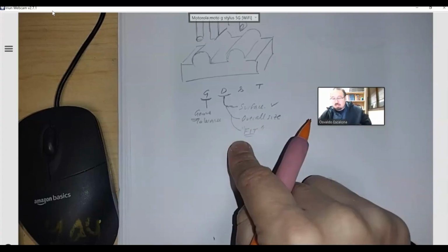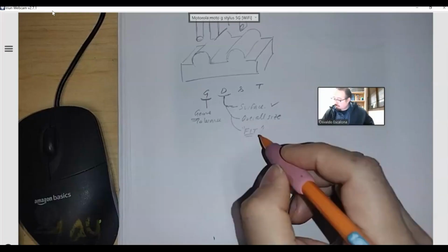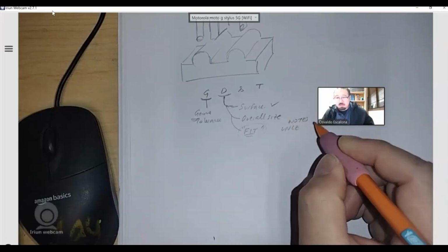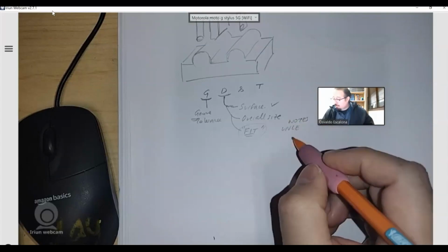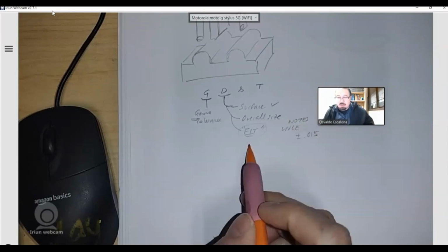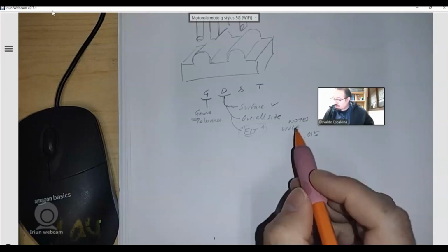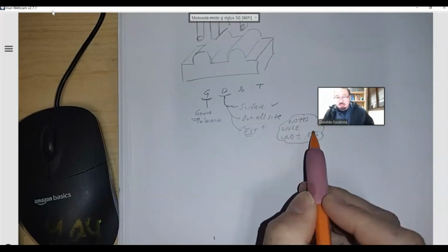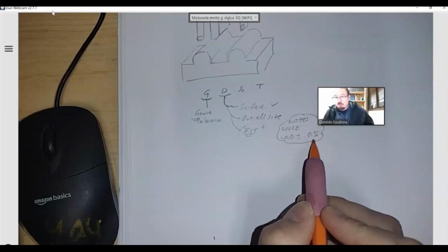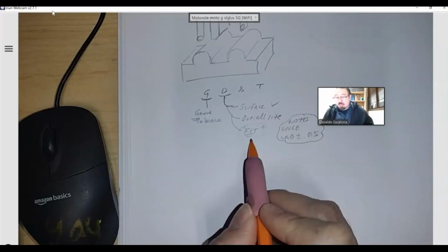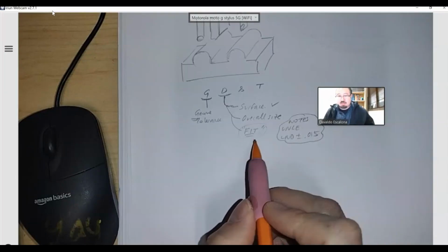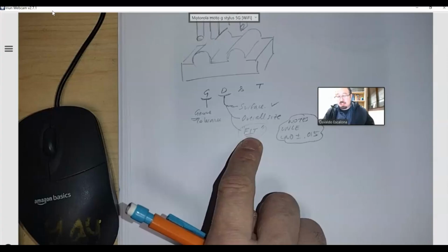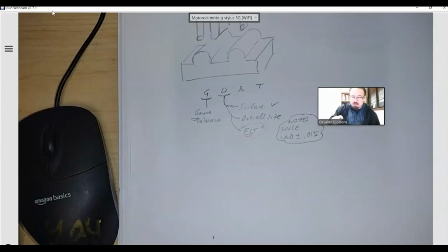The numbers that are otherwise, you guys have seen this before. Unless otherwise specified in your notes, you're going to put plus minus 50 thousandths, and for things that require a center, something that is only otherwise, again, this is in your notes, right? Unless otherwise specified, use this. If I specify it somewhere else, it's because it has a special function. And one of the functions that is going to require us to change this is how things fit with each other. Okay. So that is pretty much the lecture of today.